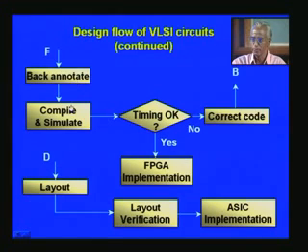So having got this, once again you have to go to step B and then do the compilation and simulation, right? So here most probably there will be no compiling error, but unless you compile you cannot simulate, right? So you have to load etc. So you enter ModelSim for simulation once again. You can straight away go to ModelSim and do the compilation right there and simulate here. So will there be any problem associated?